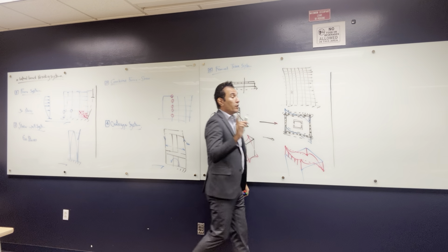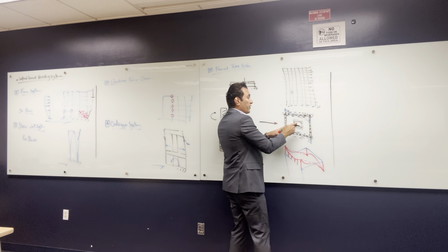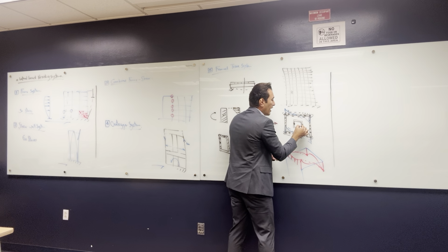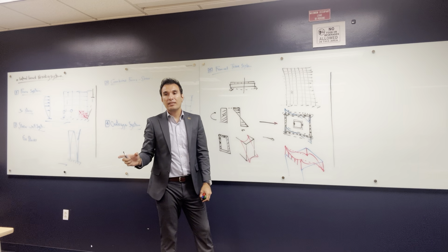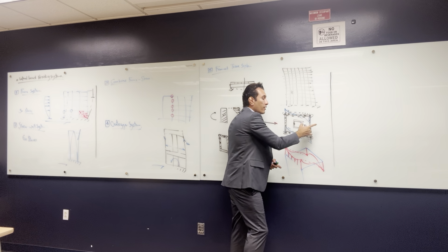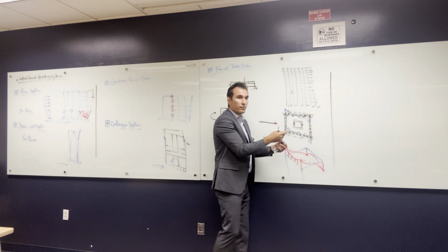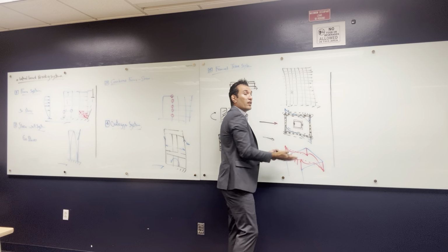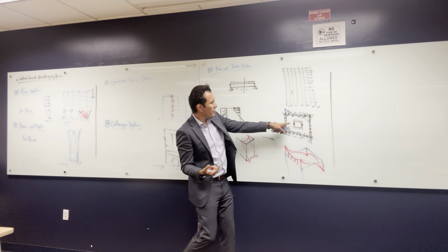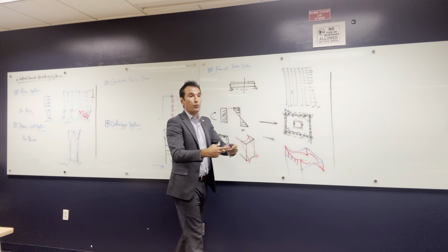All right? So there's a tube outside, right? This core and this core, we can connect them with something called a coupling beam, and this system gets named the tube and tube system. Why? Because there's a tube inside and there's a tube outside. But you will tell me, is this a tube? Yeah, this is actually a better tube than this, because you have a shear wall that is completely solid, and you just have a coupling beam. But you'll tell me, how does this coupling beam complete the tube action between the two cores?